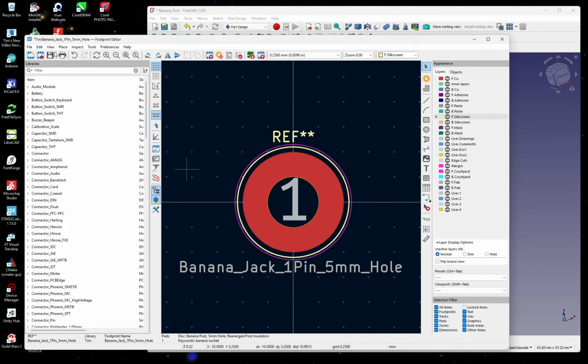We'll go this way. Components, mechanical, banana. Oh no, I've changed where I put them. I put them into connections now, so we've got banana connections. Banana post, and we should have the identifier post A. Identifier post A, and then there's the one that's black, and that's one pair. And then identifiers PP, and there's the other pair, and then there should be another one.